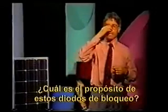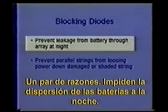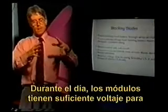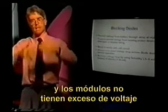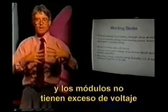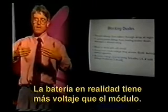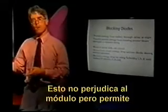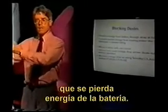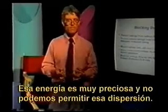What's the purpose of these blocking diodes? A couple of reasons. They prevent leakage from your battery at night back into the array. During the day, modules have enough voltage to push current through a battery. At night, there's no light. The modules don't have any excess voltage above the battery. The battery actually has more voltage than the module. The battery could pump current backwards through the module. This doesn't harm a module, but it does allow for energy loss from your battery. That energy is pretty precious. We don't want to allow that leakage.